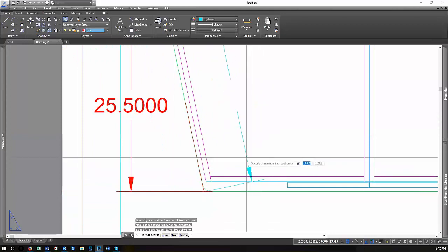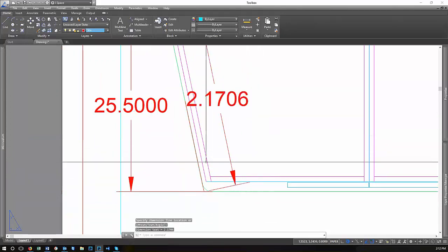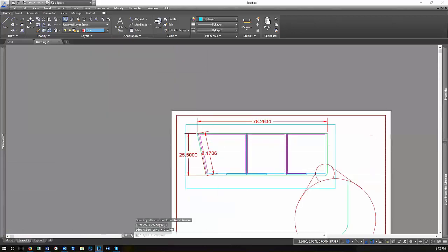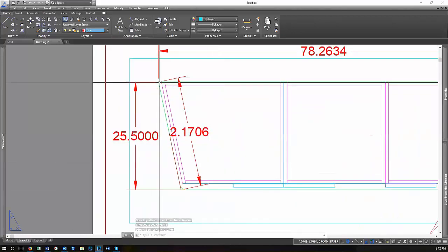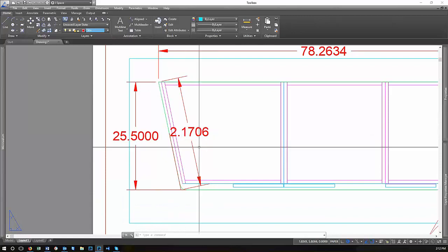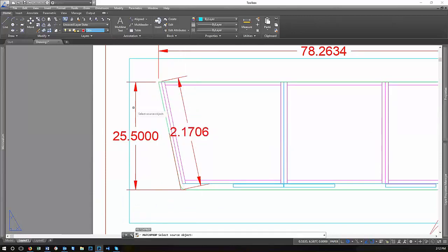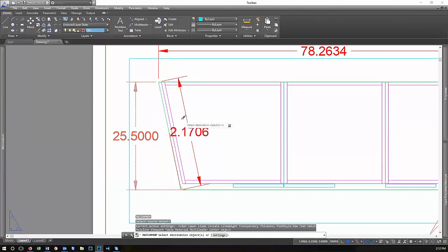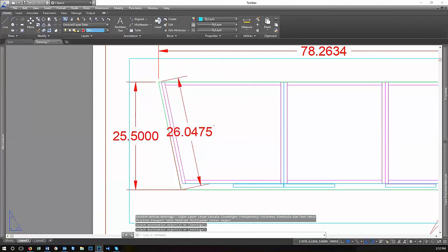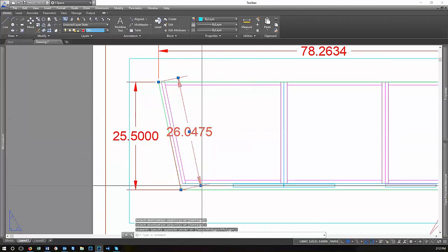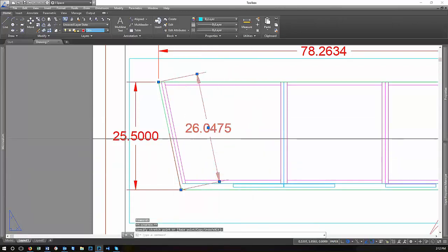It's coming up as 2 inches because I'm snapping to a point that's in paper space. So in paper space, this is 2 inches from here to there. I don't care what it is in paper space. So I'm going to match properties to this other piece of text, and it's going to swap that for using the dimensions for model space, because this one's set.